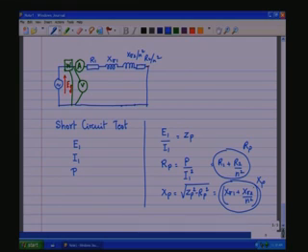XP gives the total leakage reactances of both the primary and the secondary side reflected onto the primary side, as seen on the primary side. So, this gives you the leakage reactance, and this gives you the equivalent winding resistance. So, the short circuit test can be used for finding these two parameters. As N is known, one can also find out the other parameters.